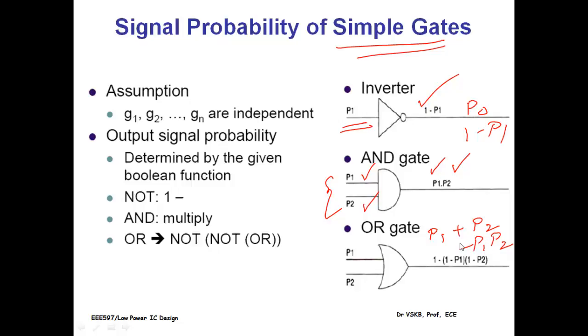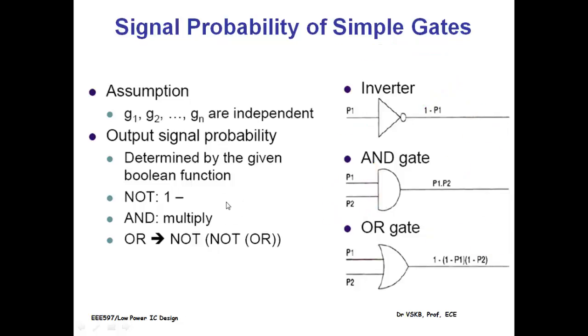With this information, I would go for considering any particular logic signal with certain inputs happening through the circuits. I go through the gates, the Boolean functions, whatever I have implemented, I will have the data passing through, their probability, their transition frequency, everything reaching the output. There I measure. So if I want to have a very accurate calculation of the power, naturally I could traverse across each of these input paths to the output and identify.